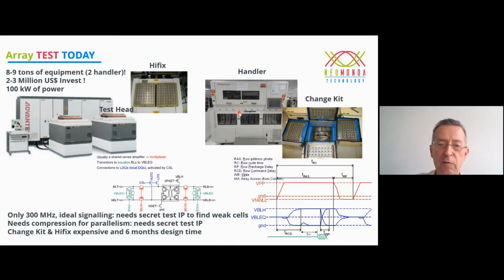The purpose of this array test is only to test the memory cells. An 8 gig DRAM with 8 billion memory cells. You travel through all those cells, ensure certain environment around this cell. If you want to test for leakage, depending on the leakage mechanism, maybe a 1 in the memory cell and zeros around it to stress cell-to-cell leakage.